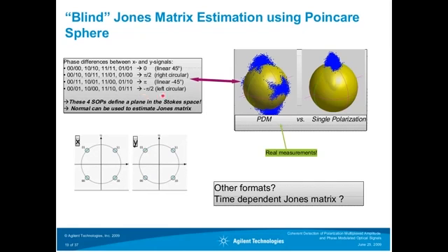So this means you have left circular light. So in total, you have only 4 states of polarization coming out of your QPSK polarization multiplex transmitter. And those 4 states of polarization represented in the Stokes space represent those 4 points. And those 4 points in turn define a plane. And the normal of this plane you can use to do an estimation of your channel.